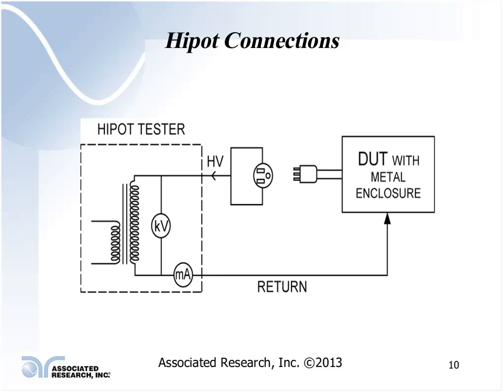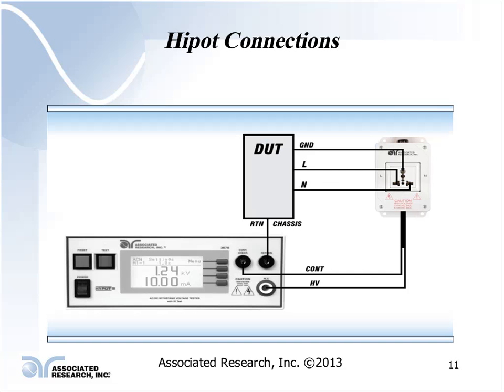This is accepted by most of your safety agencies. They typically do not like you just shorting high voltage to the return. They don't consider that to be an effective, good test. They want you to either have some type of known bad product that you're testing, or something where you're actually monitoring the current flowing through this circuit to make sure that it will pass or fail whenever you're going through and doing this test.